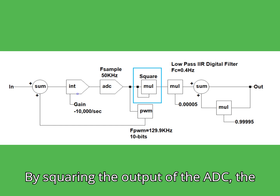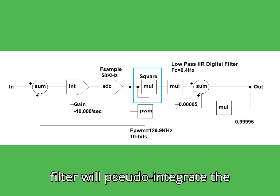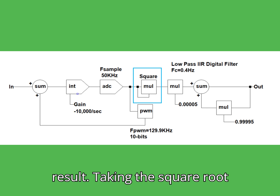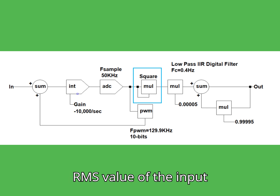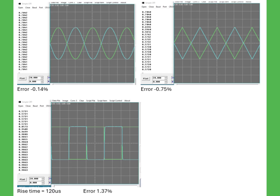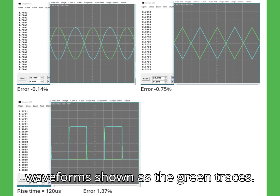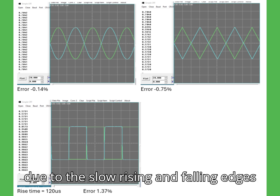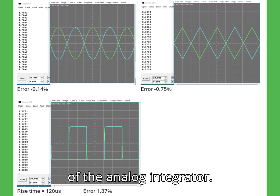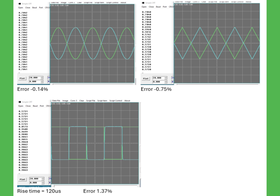By squaring the output of the ADC, the delta sigma converter's IIR filter will pseudo-integrate the result. Taking the square root of the filter output returns the RMS value of the input signal. Here are 3 1-volt peak input waveforms shown as the green traces. The square wave has the most error due to the slow rising and falling edges of the analog integrator. Blue waveforms are for the integrator output.